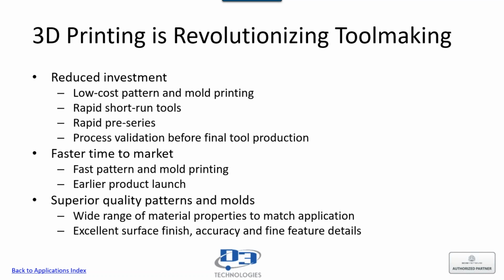At this stage of rapid tooling, the supply chain expands with purchase commitments for some of that raw material, and the lead time for these required items can really stretch out your time to market. So 3D printing in a variety of ways really does help reduce that investment risk and shorten your time to production.